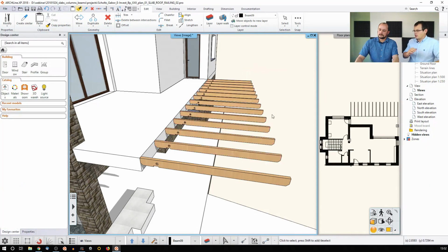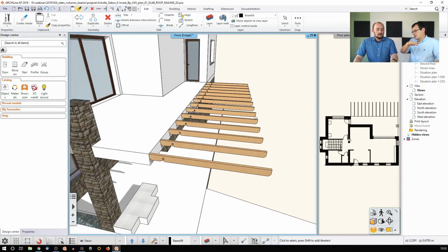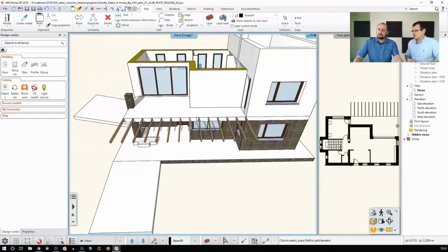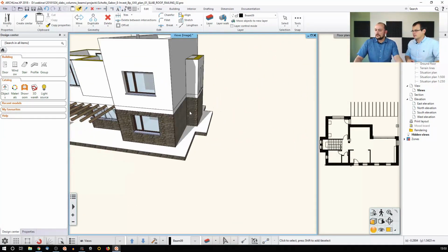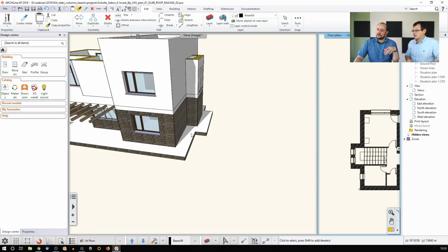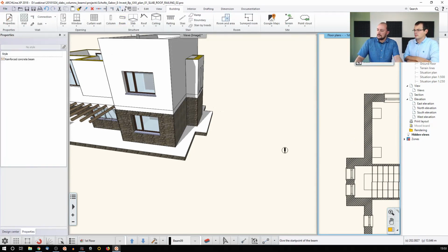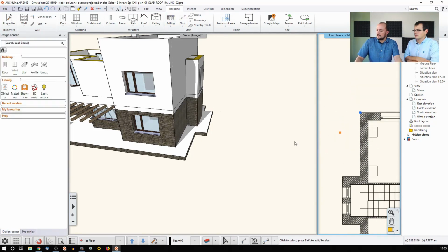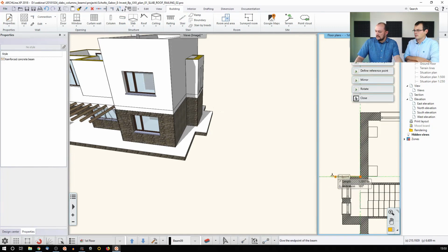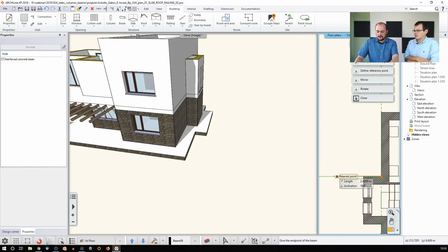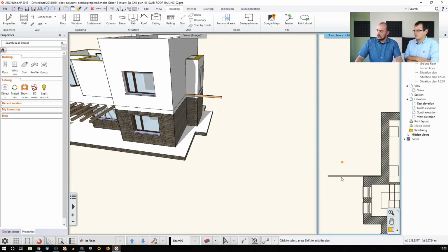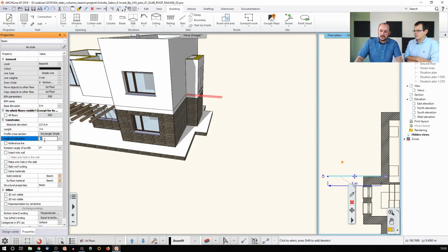Can you show how to curve the beams? I mean a curved structure out of this. Yeah, let's make a few of those. Say there's, for example, a roof for a car or something like that. So in that case, what I would do, let's just create a beam which is by default, I think I just created here. This is a beam at a position like this. It should be, I don't know, 3 meters long. And it should be inclined a bit, so I just change it to, I don't know, 10 degrees.